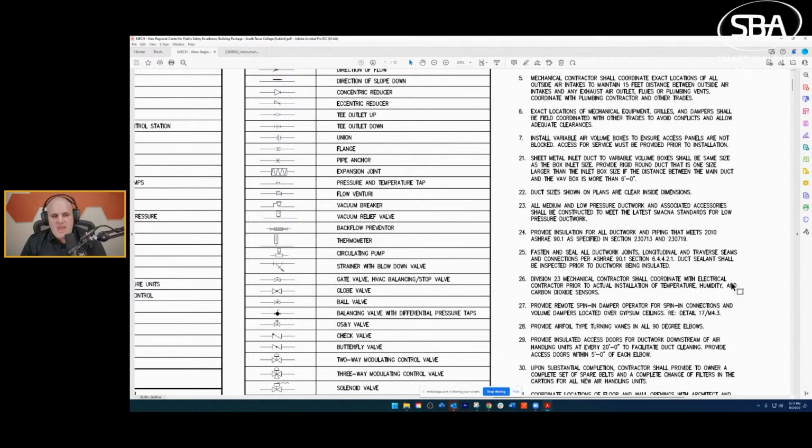Well, if you had actually coordinated with the electrical contractor, you might have been able to get some stub ups in the mechanical rooms and in the slab. You may have been able to coordinate some potential stubs for your electrical that are in your walls, etc. It really just depends what's in scope for people. But this coordination is going to save you relocation.